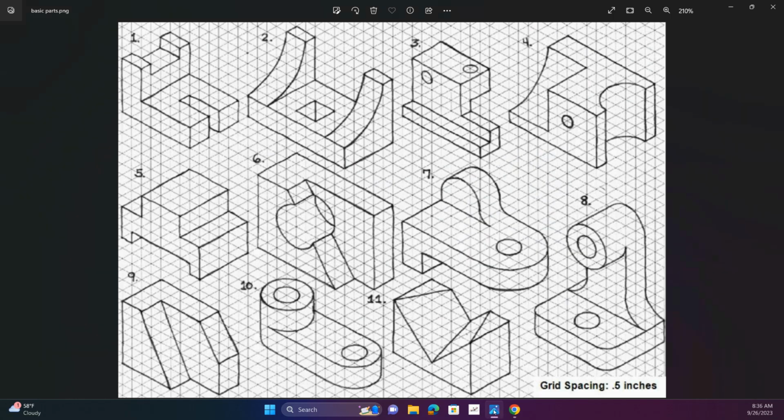If I go back to this picture here, I can see that it's going to come down ½ inch, 1 inch, 1.5 inch, 2 inches. And I've got an inch on either side. So it's a 5 inch total length, which means this is going to be 3 inches because I have an inch here and an inch here. So I'm going to come down 2 inches. It's going to be a 2 inch by 3 inch rectangle on the back of it.